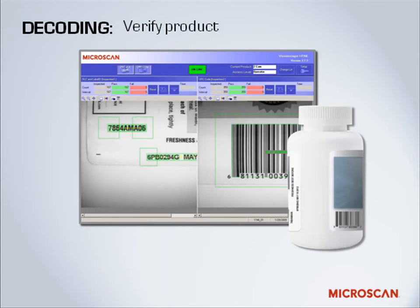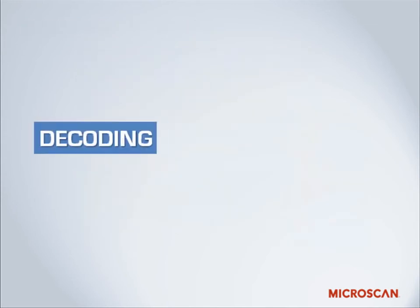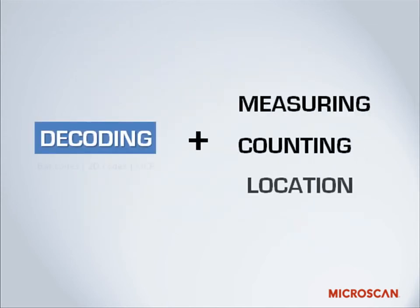An obvious question here is, why use machine vision to do this, when dedicated auto ID systems would do the same thing? You might think of machine vision as auto ID or barcode reading plus. The plus is the ability to run other measurements and operations in combination with the reading of barcodes or text. For example, you might want to read a label and also check that it's properly aligned to the product.